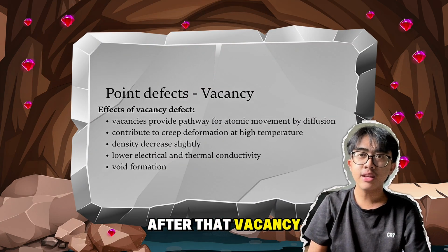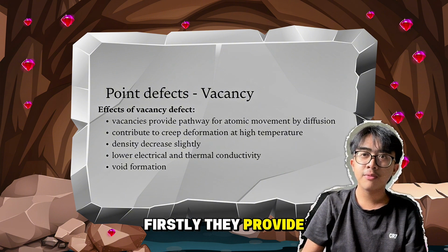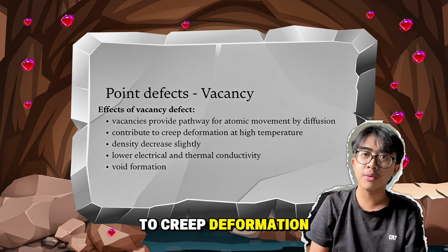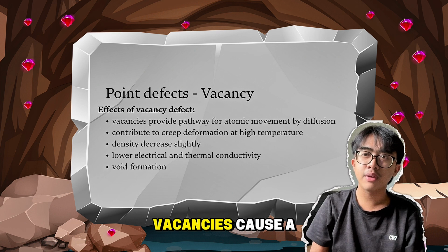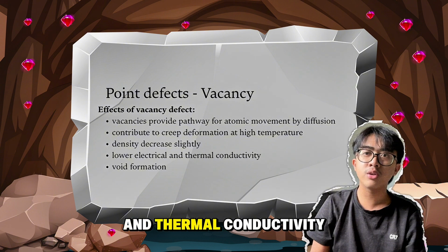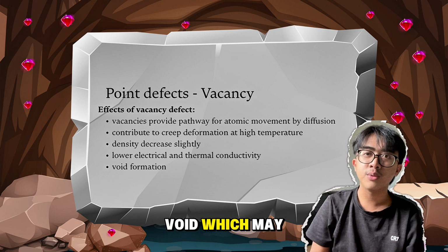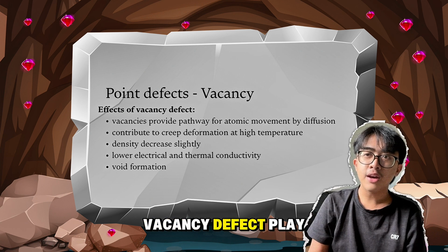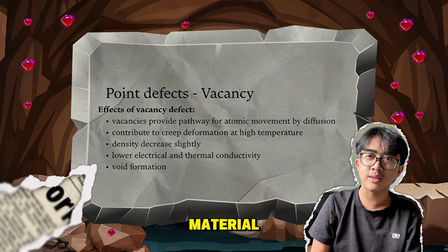After that, vacancy defects have several important effects on materials. Firstly, they provide a pathway for atomic movement through diffusion. They also contribute to creep deformation, especially at high temperature. After that, the presence of vacancies causes a slight decrease in density and reduced electrical and thermal conductivity. When many vacancies combine, they can form voids, which may weaken the material. To sum up, vacancy defects play an important role in determining the mechanical and physical properties of materials.